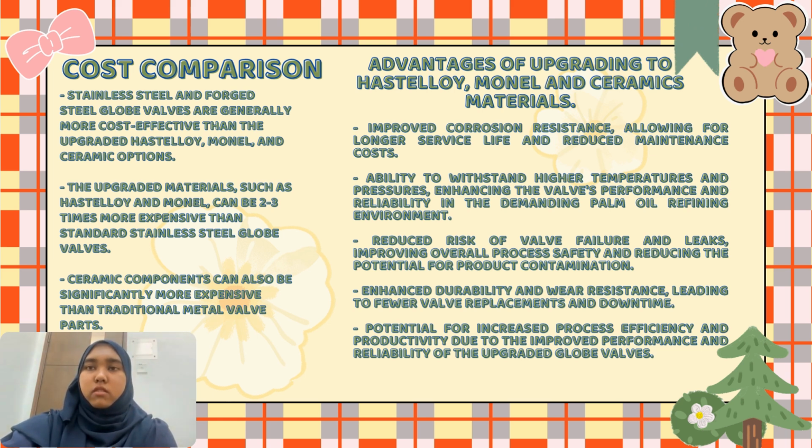The upgraded materials such as Hastelloy and Monel can be 2 to 3 times more expensive than the standard stainless steel globe valve. Ceramic components can also be significantly more expensive than traditional metal valve parts. Next are the advantages of upgrading to Hastelloy, Monel, and ceramic materials. First is improved corrosion resistance, allowing for longer service life and reduced maintenance costs.